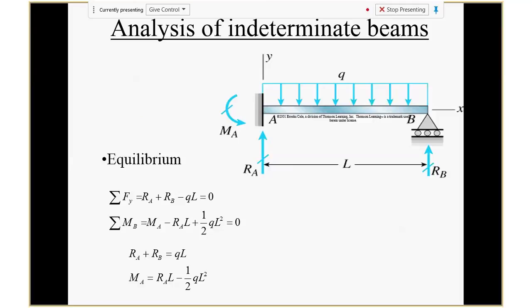Okay, so here is a beam. We cannot call it a cantilever beam anymore, right? It's not a cantilever because there's an additional support there. So it's a fixed-pin end beam. First, is this determinate or indeterminate? Indeterminate, because we already covered this.